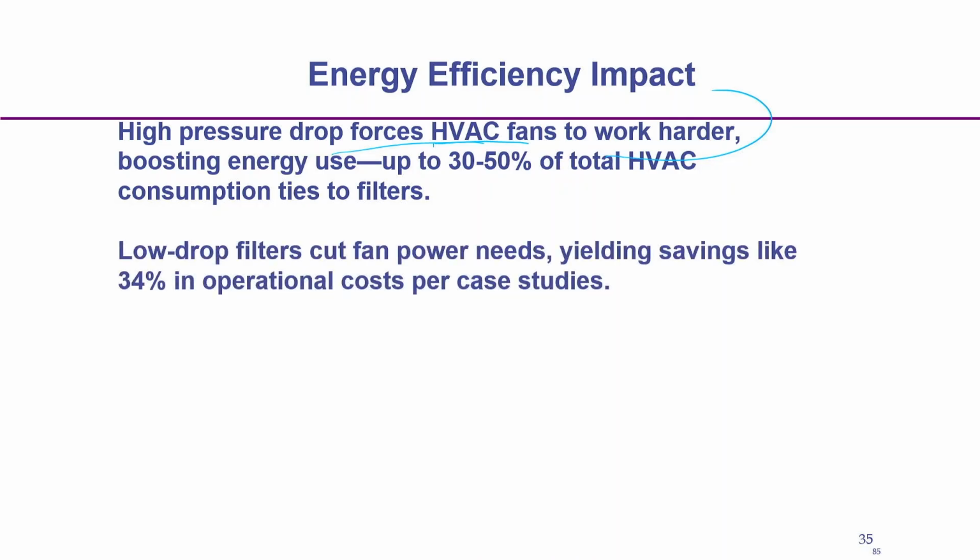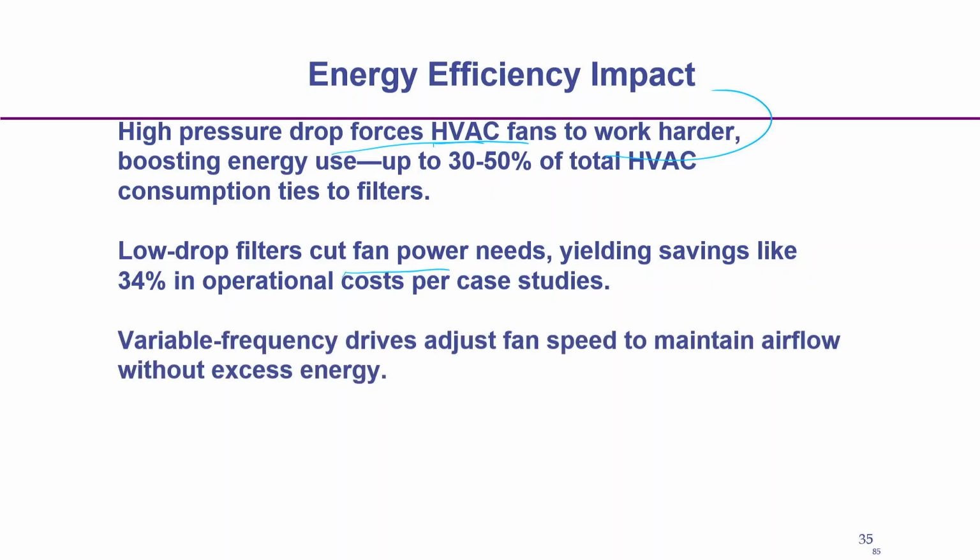A low pressure drop cuts the fan power needed. So, if the pressure drop is low, then we can save power because of the lower energy required. That is why we normally use a variable frequency drive, just to maintain the air flow.